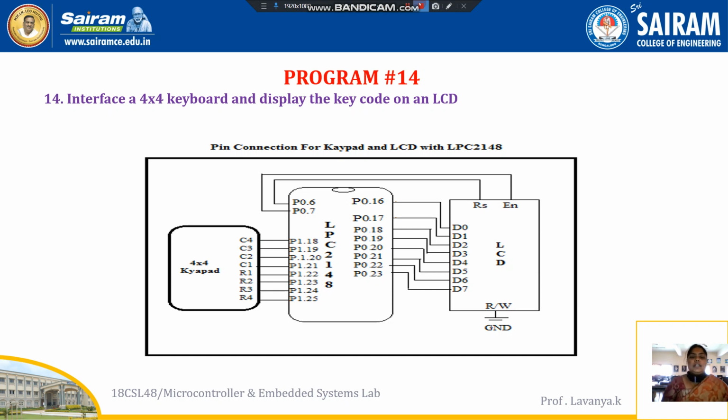See, these are the pin connections for the keypad and LCD of our LPC 2148. Here I have taken the number of columns and rows, along with 8 data lines that I am going to connect from the LCD display kit to our ARM controller board, the LPC 2148. Whatever data is displayed on the LCD has to be retrieved from the ARM controller board, and only then is it displayed as output on the LCD display.